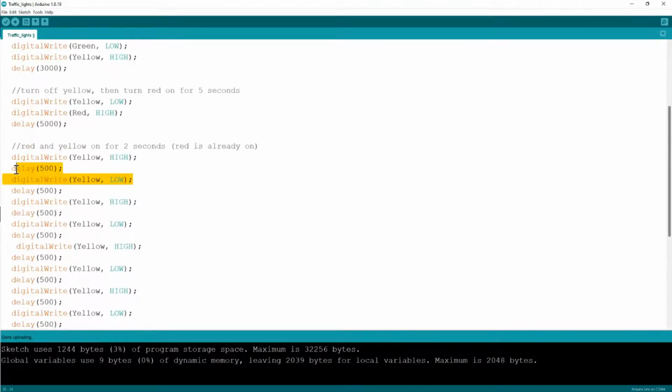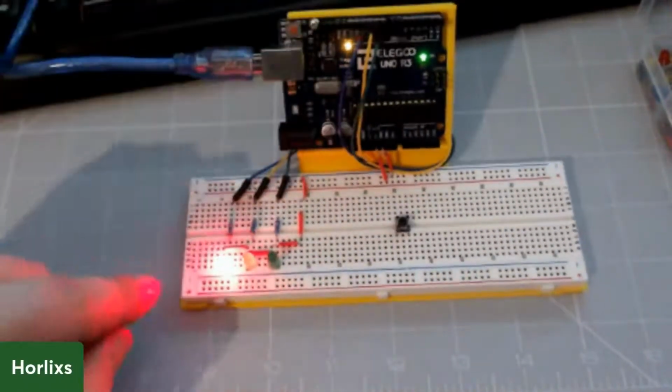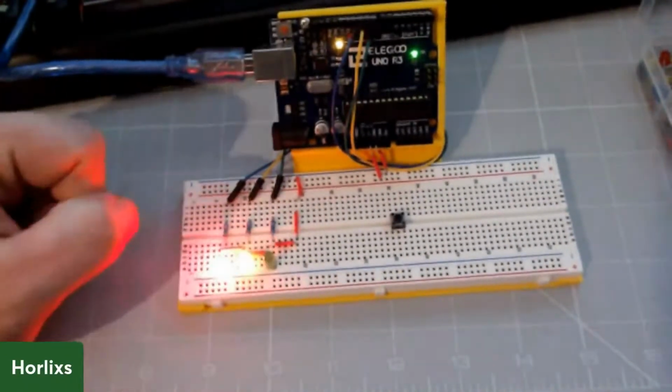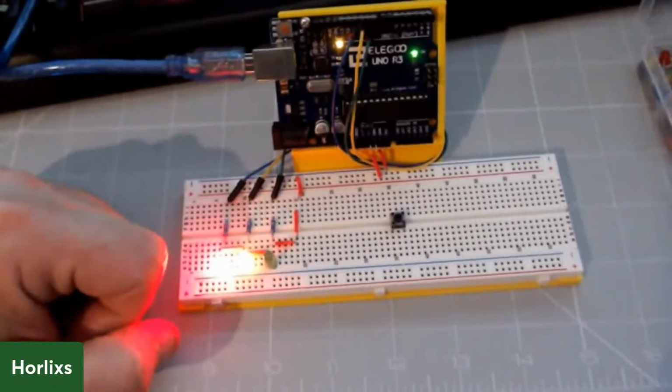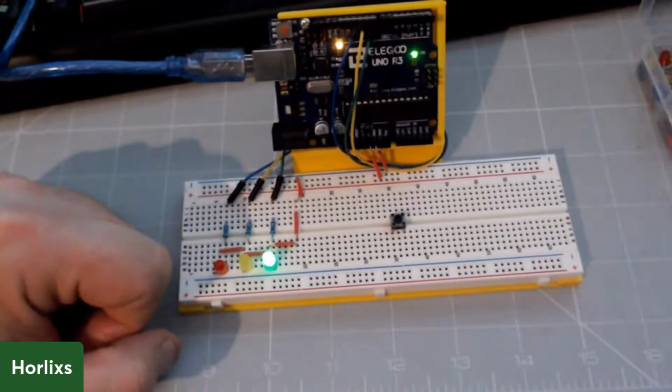You can play with that yourself. All you have to do is copy lines, just play with it. As long as the circuit's right on the actual Arduino, once you've got this bit wired in right, you can play around with this code as long as you like. Change times. You could change this down, make it 100, make it flash really fast.